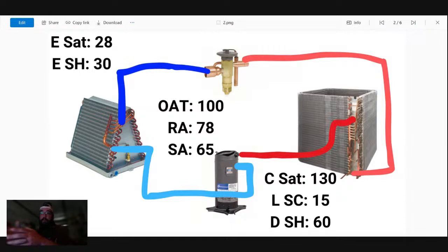And that's part of what happened in this particular case. By actuating the spring, we changed things enough internally that it allowed it to break free. So basically, the push rod stem in there that the power head pushes against was able to come loose, and now it's fluctuating again like it needs to.